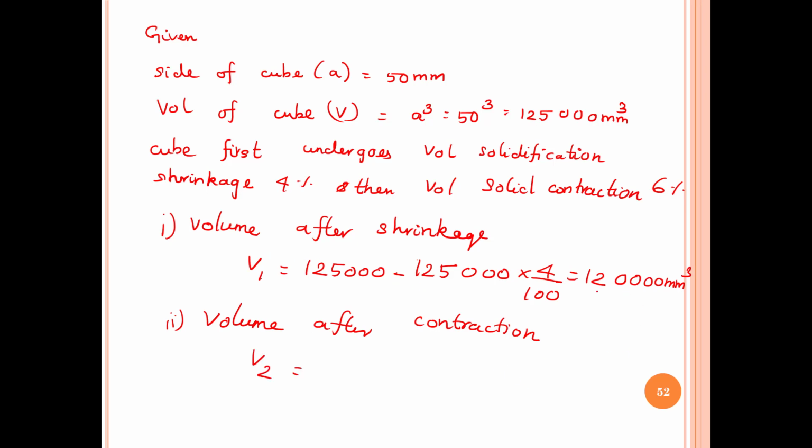Now this is the volume as of now: 120,000 minus the volumetric solid contraction of 6%. That is equal to 112,800 mm cubed.